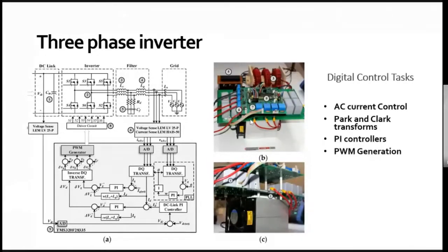There will be a control loop inside the microcontroller. It will generate output parameters. Based on that, it will generate a PWM that will be fed into 6 switches. That is a three-phase PWM inverter. Those 6 switches will generate proper sinusoidal current to the grid. Exactly similar to single phase, but there will be a three-phase current injection system that will be controlled inside the microcontroller using a different algorithm. I am discussing this just because here there will be different transformations and a different control algorithm used, rather than direct control in single phase.